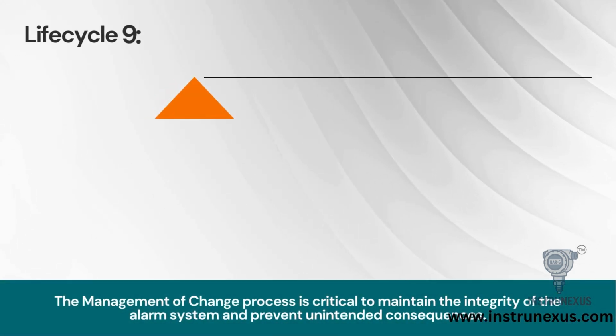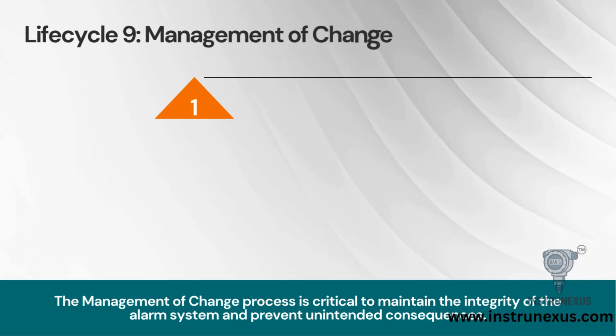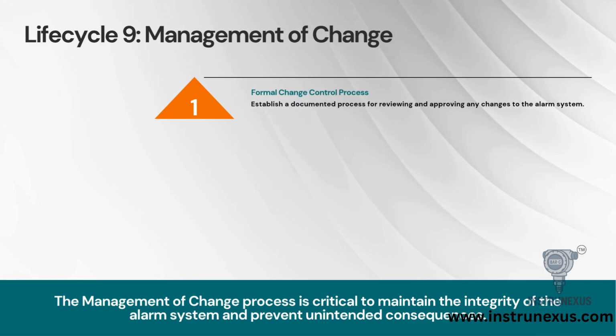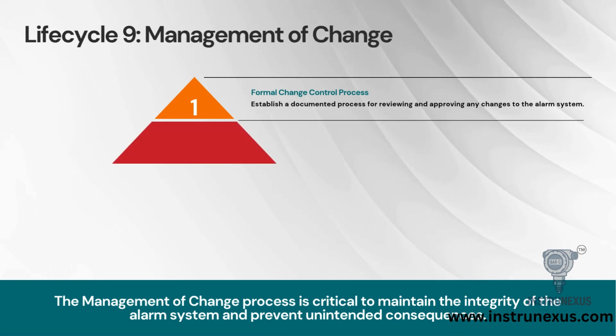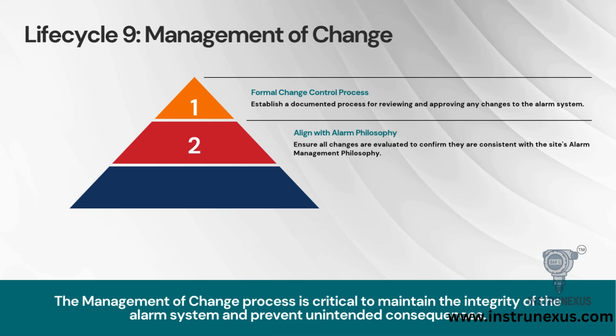Stage 9 is management of change, or MOC. This is the shield that protects your rationalized system. We need a formal change control process. We cannot allow just anyone to add a new alarm or change a set point because they feel like it. Any change must be reviewed and approved to ensure it aligns with the alarm philosophy.